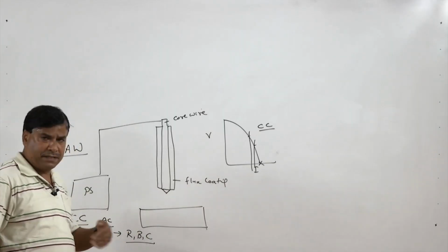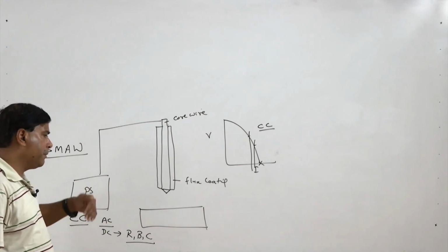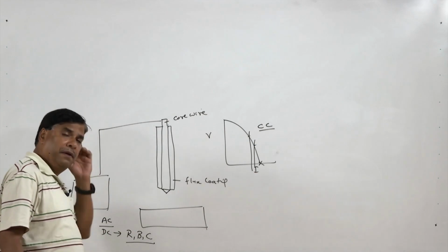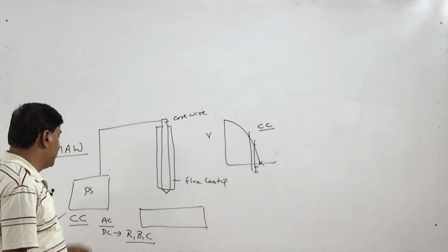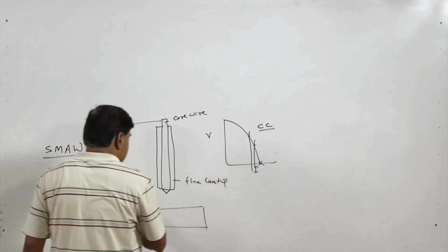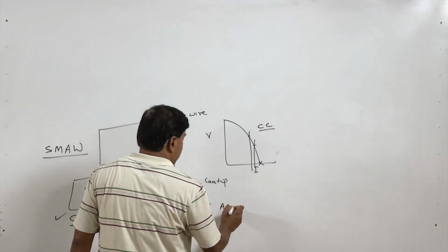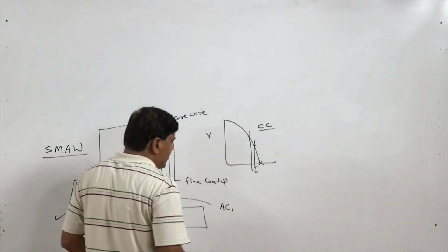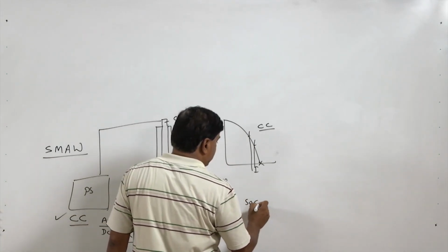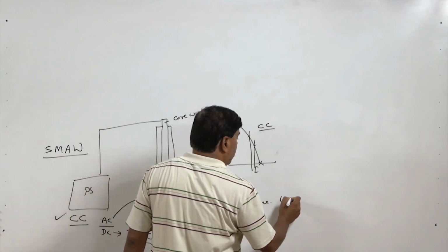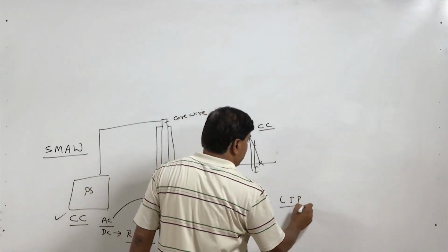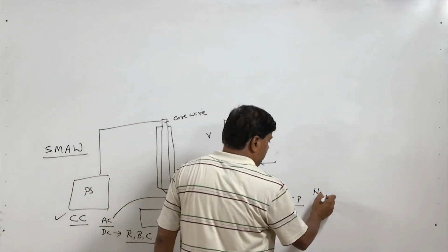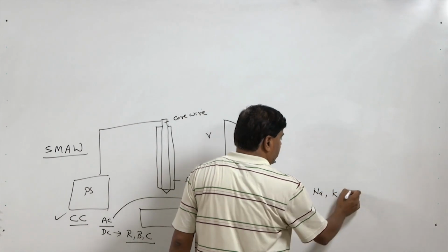All these electrodes are extremely common in the industry for welding purposes, and these can easily be used with DC welding current. For using AC, the welding electrodes need special care, especially in terms of low ionization potential elements. These low ionization potential elements must be present in the electrode in sufficient quantity, like sodium, potassium and calcium.